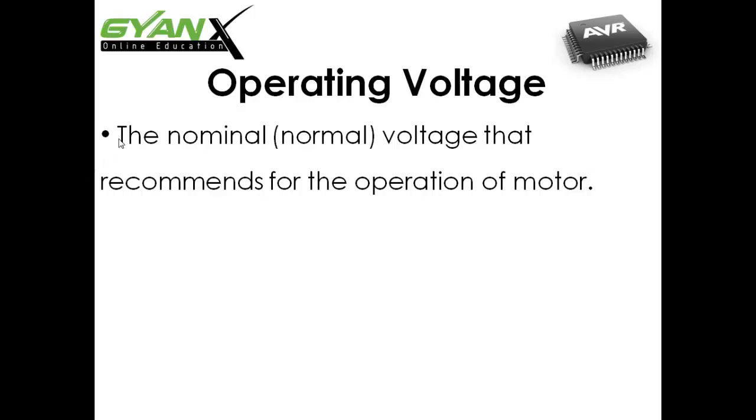Let's suppose most small DC motors are designed for 1.5 volt to 12 volt operation, with the majority in the 3 to 6 volt range. Larger DC motors designed for heavy duty applications usually require 12 to 24 volts, with some needing upward of 90 volts. Often but not always, the higher the voltage, the more powerful the motor. Most motors can be run at an operating voltage higher or lower than the specified rating.